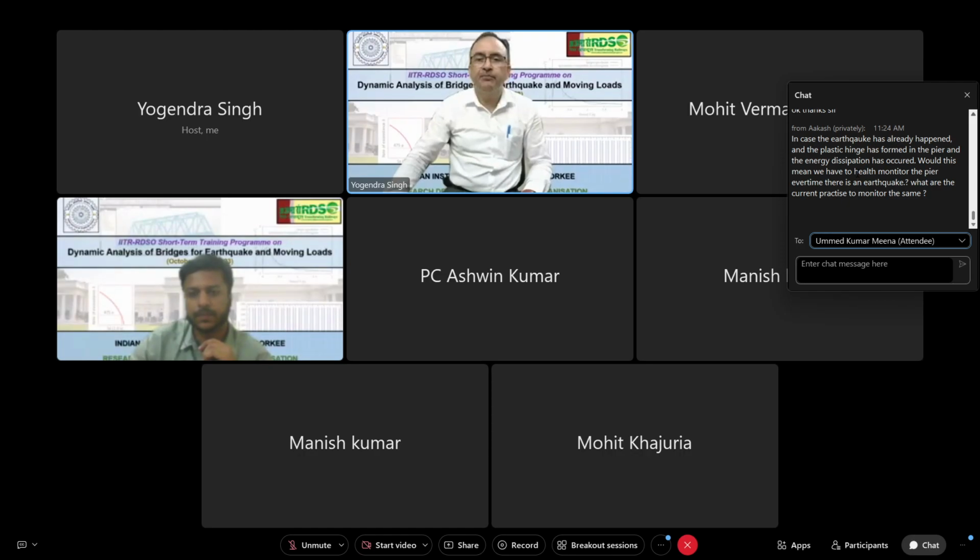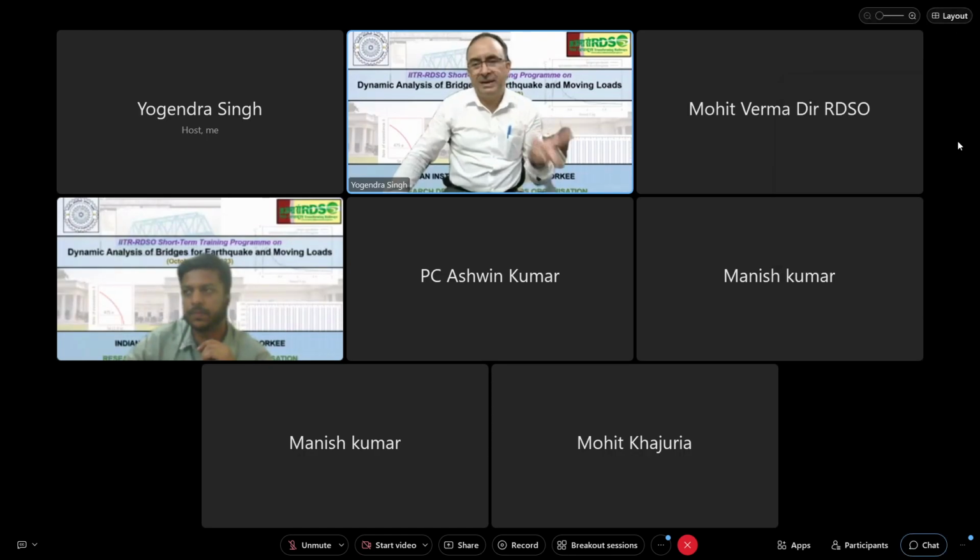Some people say that a pile, when I was talking about pile foundation, is also like a column, and we can design those piles also to develop hinges. But the problem is inspection only. It will be very difficult to inspect the piles after the earthquake to see what has happened there. So that's why we limit our plastification or plastic hinge formation or the damage to the base of the pier, and that we can inspect.